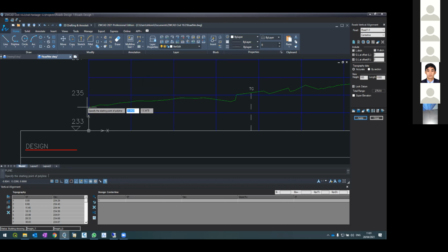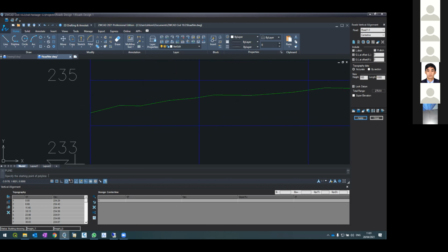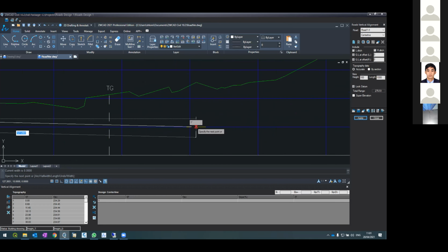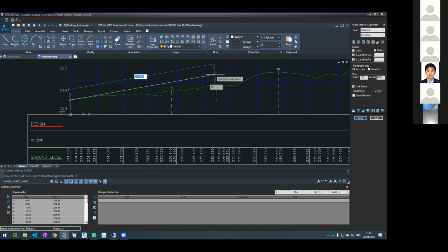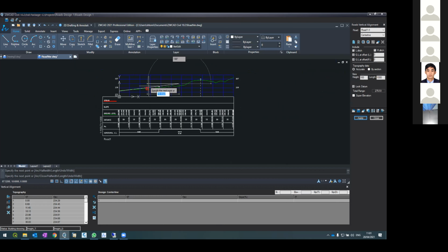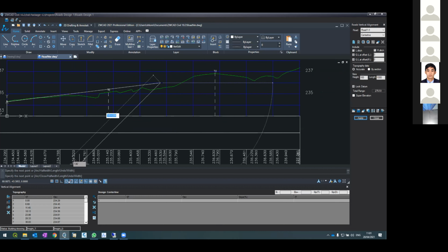And let me start somewhere. I can even start with the object snap, with the point here. How do I do it? Object snap into here. And from here, I'm, let's say, going like this. You see this is the ground, but the road will go with this slope, more or less. And from here, let me turn off the object snap.